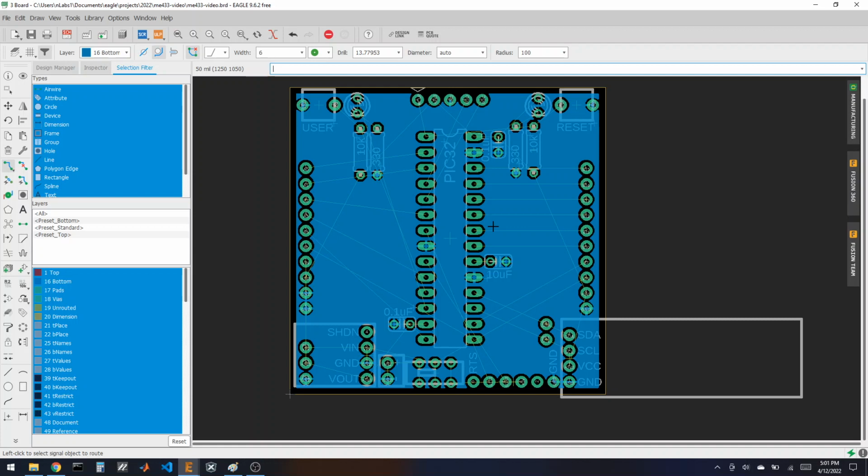We probably want to stick to some kind of consensus. We've got a lot of side-to-side connections here. Let's make all the left ones. We have to pick whether they should be in the top copper or the bottom copper. Not sure if it makes sense one way or the other, but we should be consistent. So why don't we make everything that goes left to right? Let's start on the top layer. Let's see how it goes.